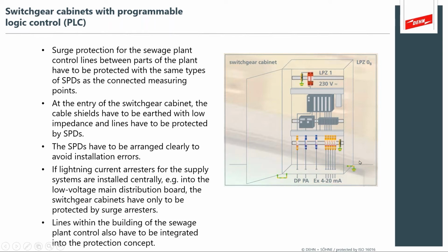You have in one illustration the requirements to show the cabinet grounding, the loose metal, for instance, the door of the cabinet needs to be bonded as well. And then you have to have your earth bonds for the surge protection devices throughout the electrical control system. So as I like to say, in one diagram, you have all of the aspects of bonding and surge protection illustrated.